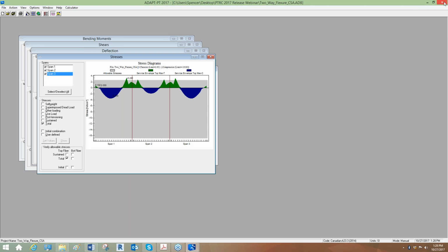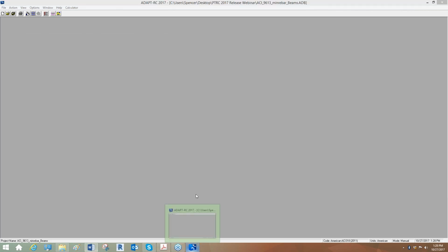Okay, the last thing we're going to show today is hybrid design in the program. Now, in past versions of the program, the user could always go in and set up a model and blank out the tendon A, add tendon B or C, and create a gap between both tendons B and C, let's say maybe for a pour strip. And you could kind of force the program to do a hybrid PT with some section being RC and then PT.